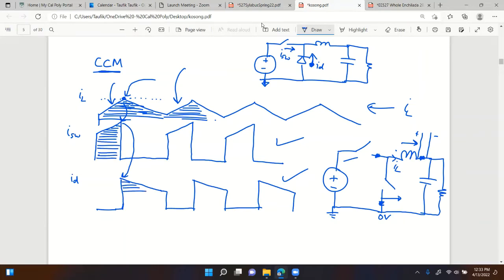Why is that important? What do you call it? An advantage by only sensing a portion of it. It contains the same info, but we are sensing only a fraction of the full current. Why is that an advantage? My hint is this resistor. What is it? Oh, the resistor has less power dissipated through it. Very good. That's why, right?